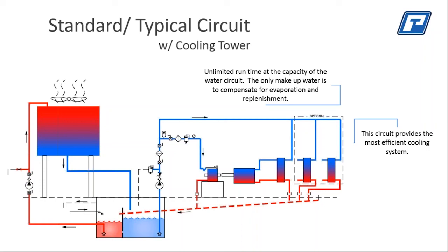Once we find that out and we size the system properly and review it, once we get to the point of quotation for a customer, we typically provide a simple water circuit, and that's what we're going to look at next, which gives you data as far as flow rates, pressures, etc. For me, I handle international customers, so I've got to deal with bar, kPa, liters per minute, etc. So I have no problem providing any data you may need, and Celsius.